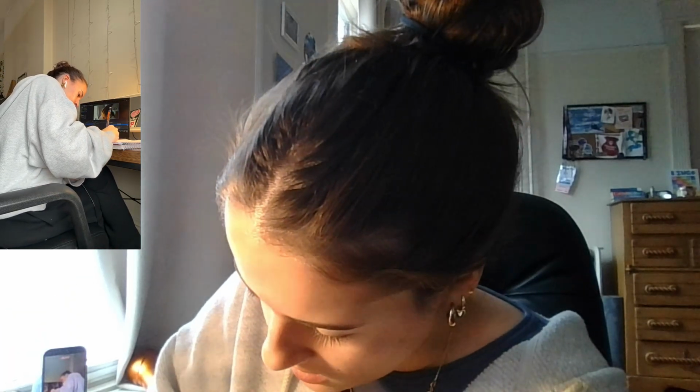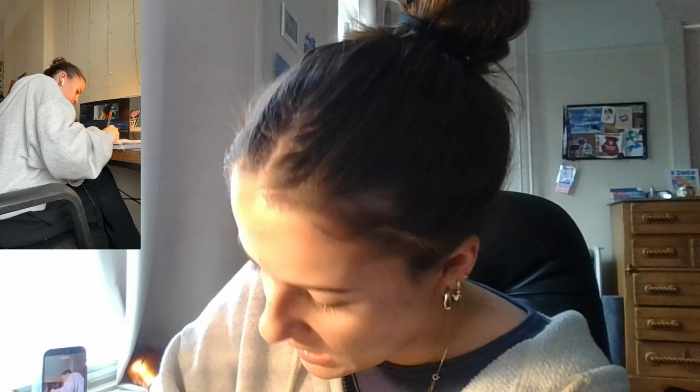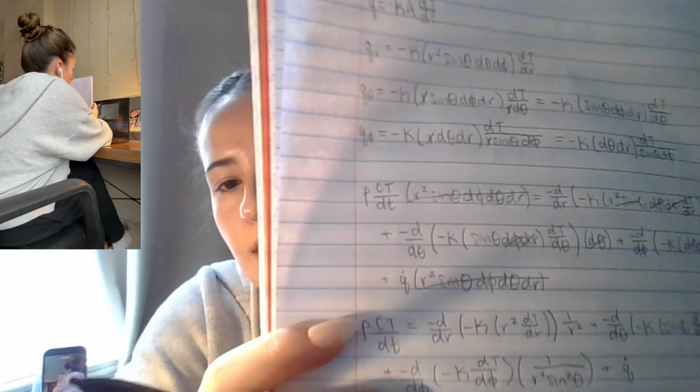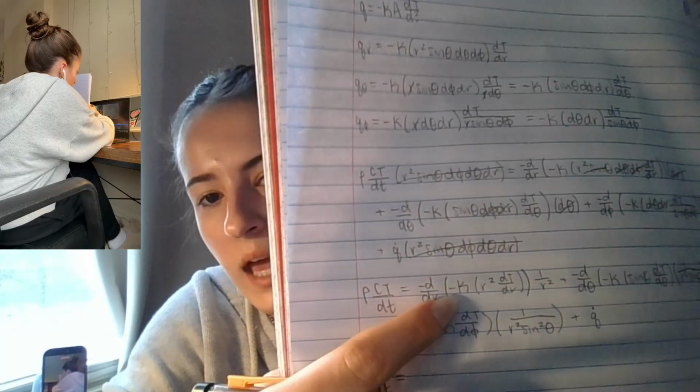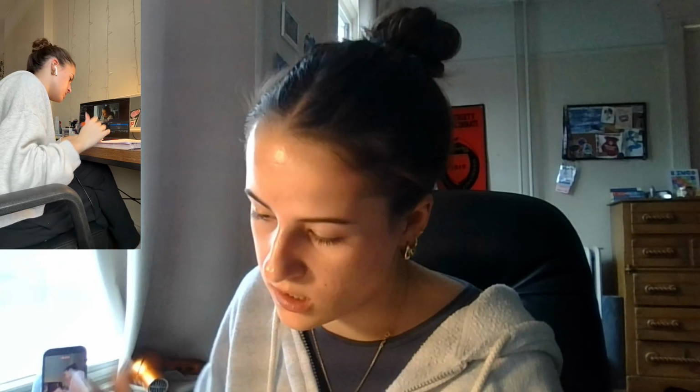We get our dT on the left side now, and we're dividing by rho C, which, as you recall, is going to turn all of our thermal conductivities into thermal diffusivity components. And once again, we can cancel out those double negatives in all of these terms and then pull our k out front for all of these because it is a constant.